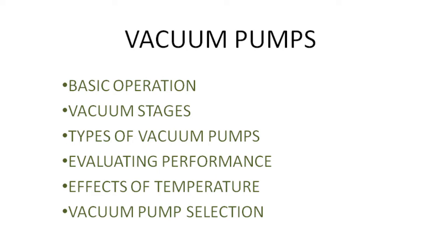Mechanical vacuum pumps use the same pumping mechanism as air compressors, except that the unit is installed so that air is drawn from a closed volume and exhausted to the atmosphere. A major difference between the vacuum pump and other types of pump is that the pressure driving the air into the pump is below atmospheric pressure and becomes vanishingly small at high vacuum levels.